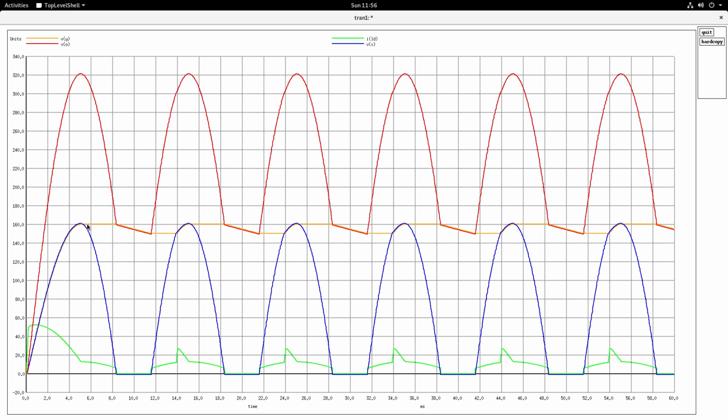Now look at this Vy here, the voltage across the capacitor. See that after it has followed the input and then come to the 50% mark, Vm/2, it then holds there till the input voltage comes below the Vm/2 point, when the rectifier diodes stop operating and the capacitors are discharging into the load. Each of the capacitors discharges into the load till again the input comes up and then crosses over here, the rectifier diode comes into operation, and then you have the output following the input.